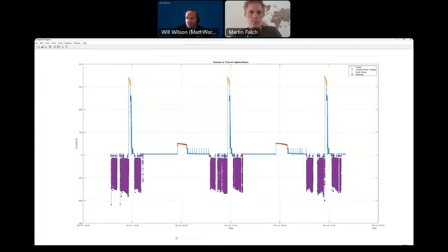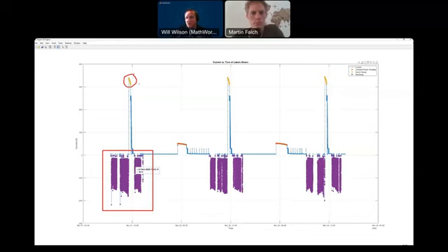So here's an example of a couple of days of data. The purple represents the machine in use. So negative current is when the machine is actually being used and cycled. And then up here we have what we're calling a quick charge event. This is when the machine gets parked and plugged in, perhaps over a lunch break, let's say, and there's some charging going on. Down here is what I call constant power charging. It's more of a slower charge, typically at night. So when the day's done, park the machine, plug it in overnight.